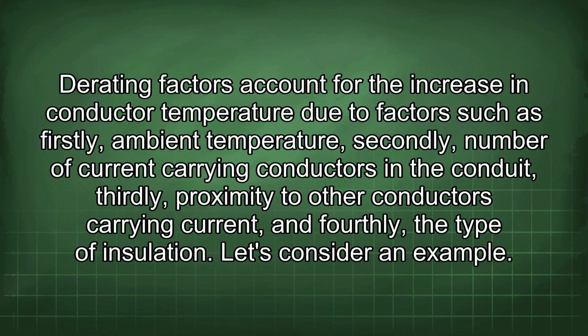Derating factors account for the increase in conductor temperature due to factors such as, firstly, ambient temperature, secondly, number of current carrying conductors in the conduit, thirdly, proximity to other conductors carrying current, and fourthly, the type of insulation.